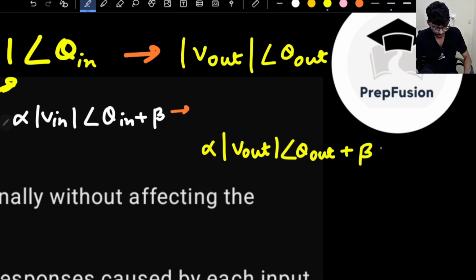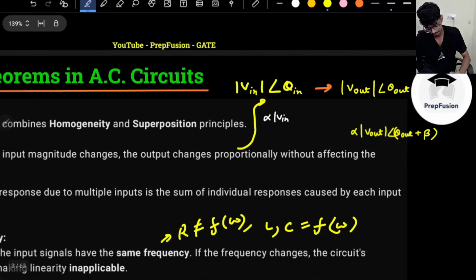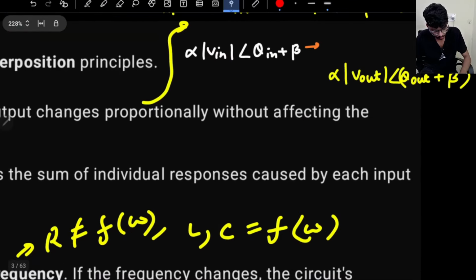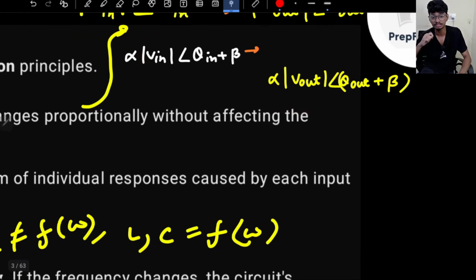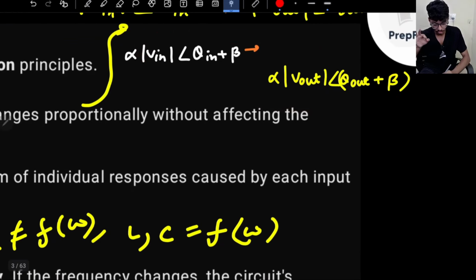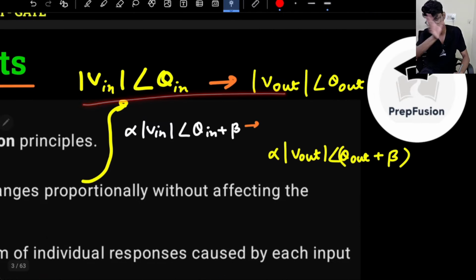So what is the important point? Again, remember, what information is not present in this phasor representation? Frequency. So the assumption is, of course, that you are discussing the same frequency component. If you discuss a different frequency component, then this will not be valid. Just be careful. For a different frequency component, first you have to write this relation, then again you can do the same thing.